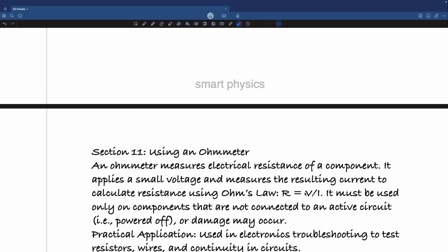And by measuring the voltage applied and the current flowing, you can calculate the resistance. That's what the meter does. It just calculates it for you. So whenever you use an ohm meter, it has a battery with it. And so it is sending a current through whatever you want to measure. And then by measuring the current, it's giving you the value of the resistance.